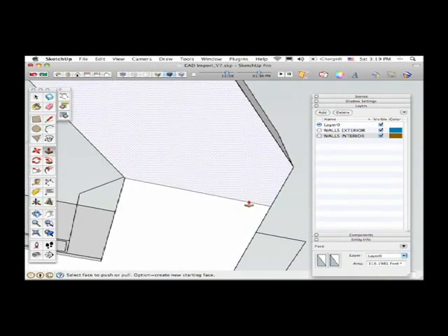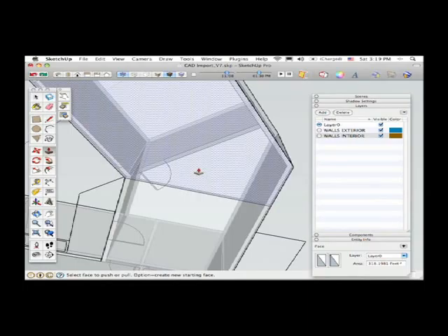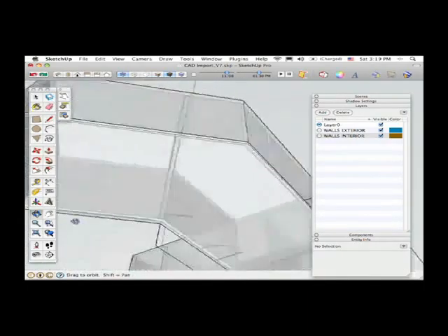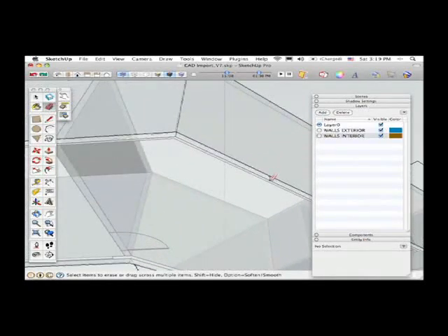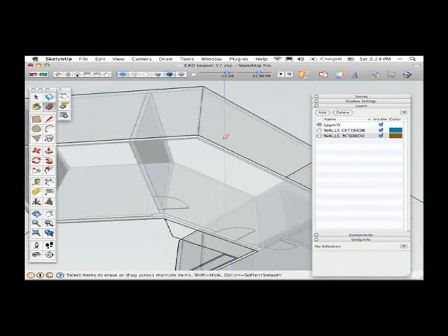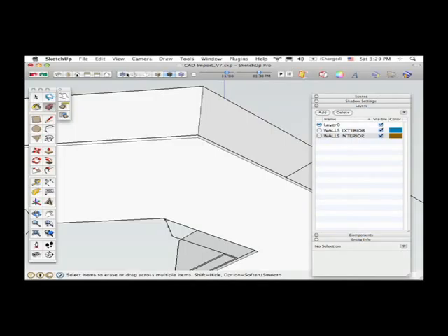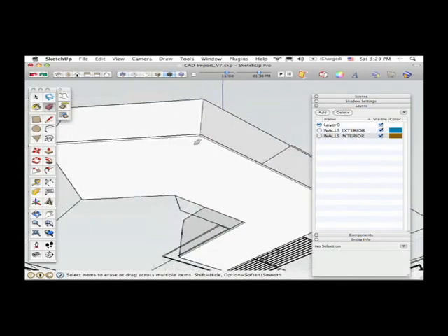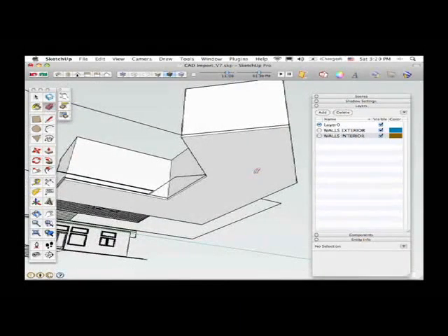Again, if I go into X-ray view mode, here I have it set as a keyboard shortcut to the letter X. I can take the eraser tool, which I have set to the letter E, and then erase the extra edges that are dividing the slab up into a couple of pieces. Turn X-ray off, just hit X again, or if you don't have it set as a keyboard shortcut, you've got the toggle up in the display menu bar. Good start for the floor.